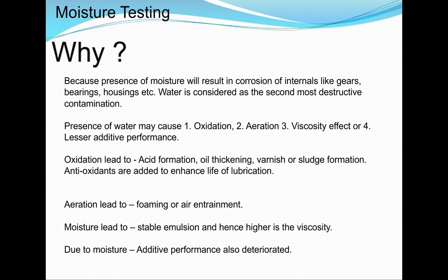Whatever additive we have added as per our requirement of the lube oil, because as I have already said in the earlier chapters, lube oil selection is a must as per the design of the equipment, whether it is a high speed motor, high speed fan, high speed pump, or the load is more. As per the criteria of the machineries, we have to select the lubricants.